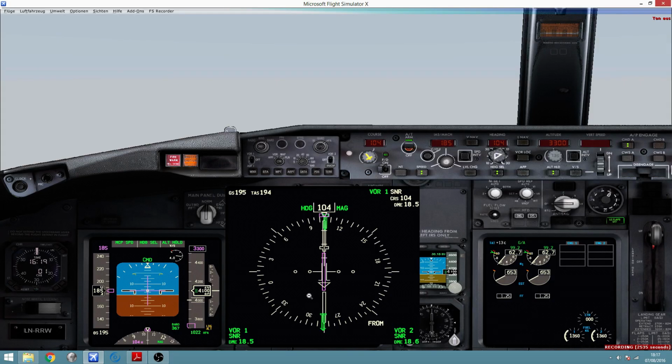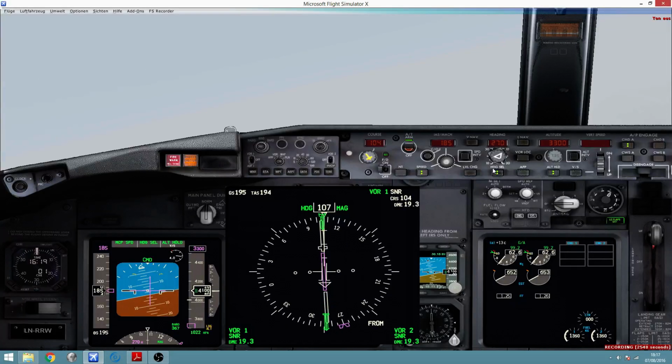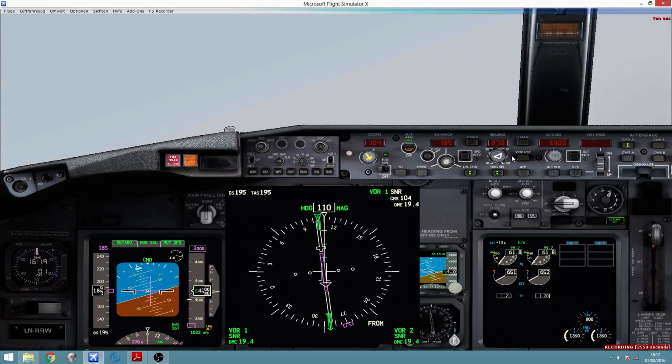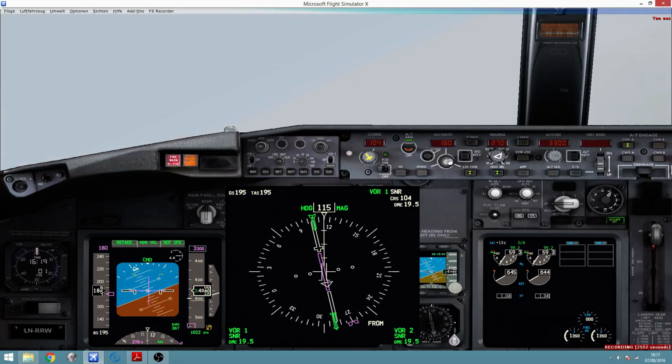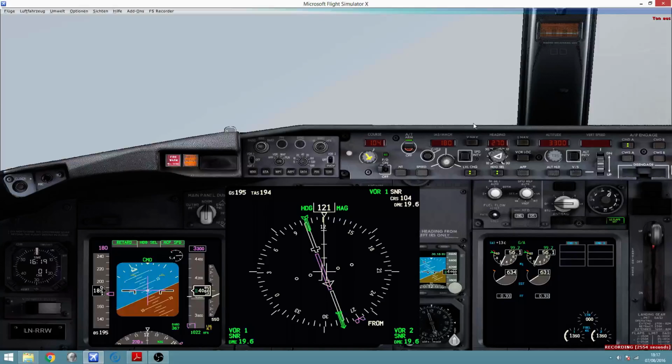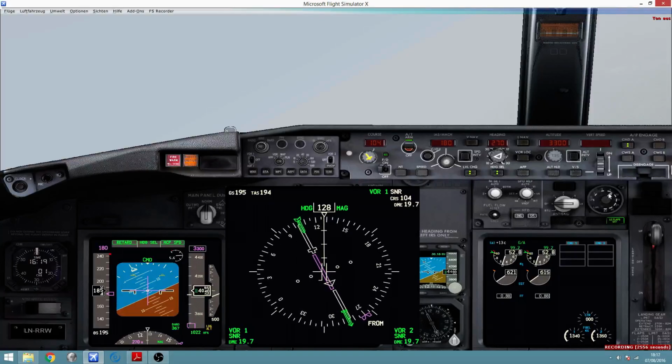Okay, so we're about to reach 19 DME out, 18.8, and well, there it goes, 19. So I'm going to turn to the right, heading west, 270 degrees. Level change down to 3,300, reducing to 180, and twice F7 to select flaps 15.